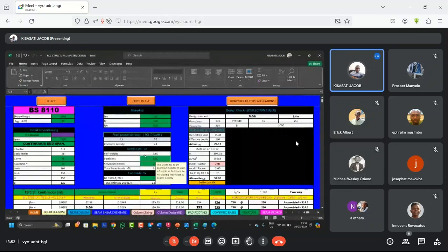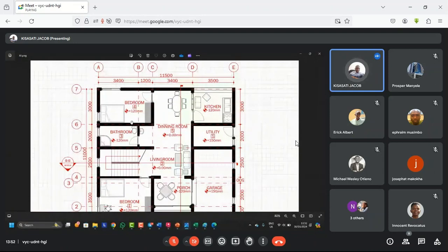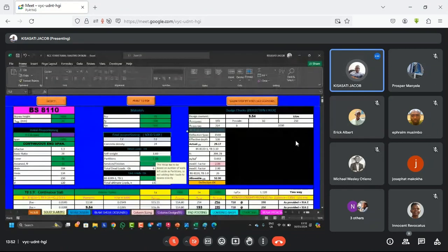The maximum value, okay, time is of essence. We have codes to tell us all this, but now write this one down. We will discuss. I will tell you the code. The minimum value is 1 kilonewton per meter squared, and the maximum 2.5 kilonewtons per meter squared. Because you are not going to leave all these walls aside as partitions, you'll have to consider some walls, just some as partition loads, and those are some of the loads that you'll now consider. So the minimum is 1 kilonewton per meter squared, and the maximum is 2.5 kilonewtons per meter squared. Please take note of that.